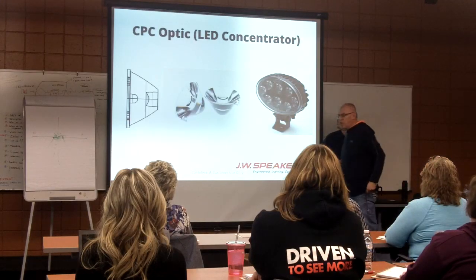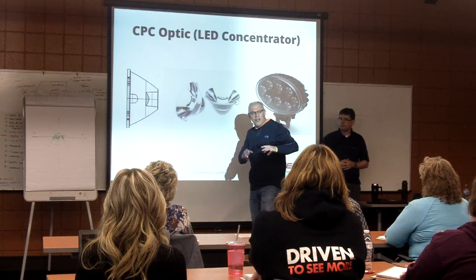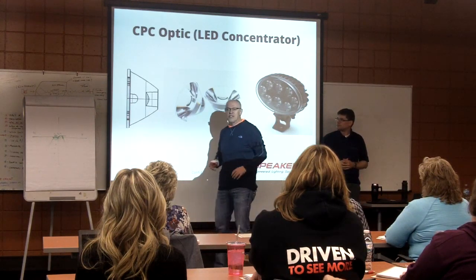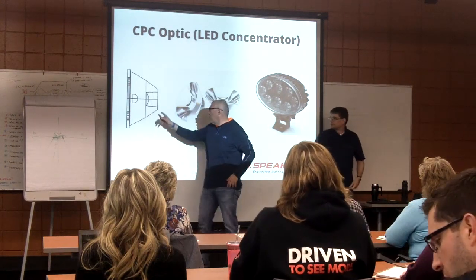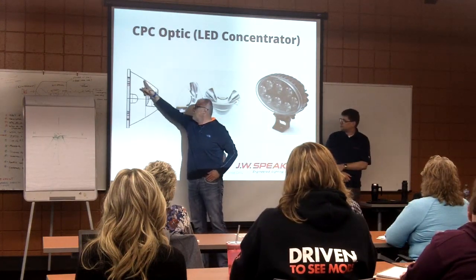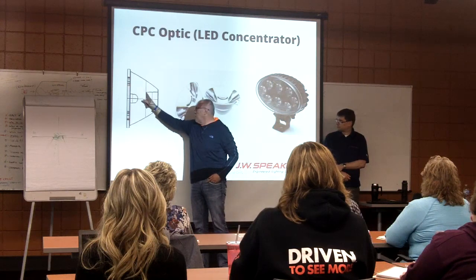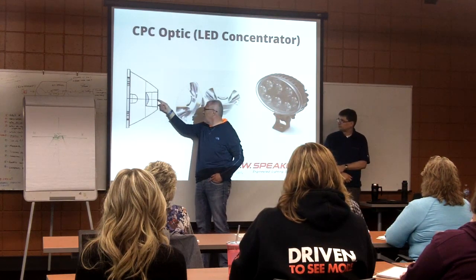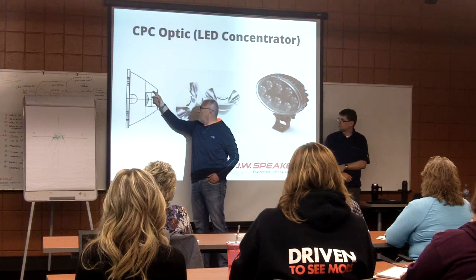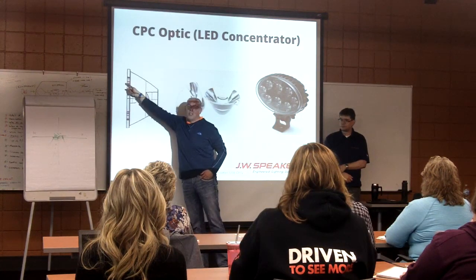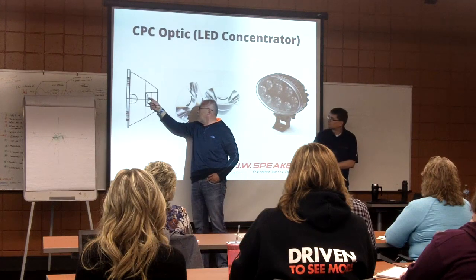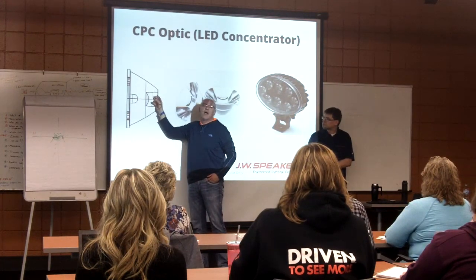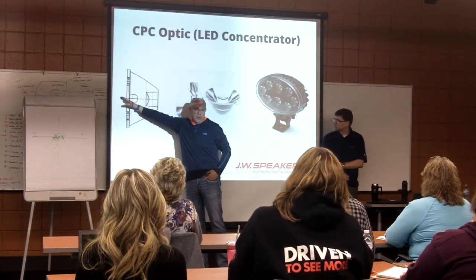This optics is a combination of the TIR. That's where people like to use TIR because it's very sound. What is happening is the LED is here. This half is working on TIR. This half is working on refraction. So basically the ray, if hitting here, refracts, hitting there, and then it's reflecting, going there. If a ray is hitting here, it's refracting, going there. So everything coming from that LED, by theory, should go out.